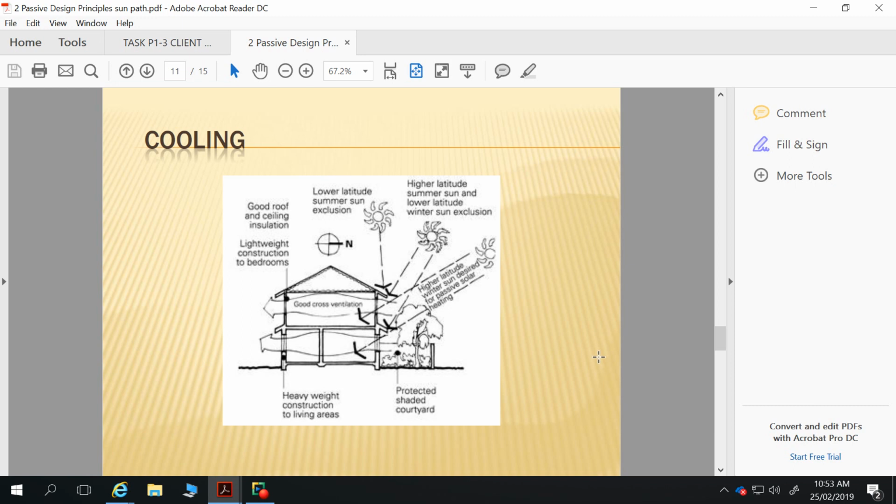If we create the separation of the sarking and the roof sheeting, when that roof sheeting is getting really hot from the sun and giving off radiant heat from its underside, it has this bit of space for that radiant heat to come off and then be reflected back from that sarking. Where we have these points of direct contact, it doesn't work.